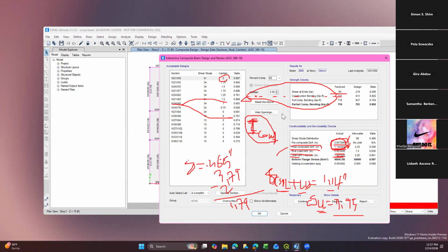So we try to use the camber to offset mostly the self-weight deflection, so that the deflection under SDL and live load is what we pay more attention to. So this calculation explains the concept of camber, right? Basically, we camber up, bend up, so that we minimize total deflection by using camber.